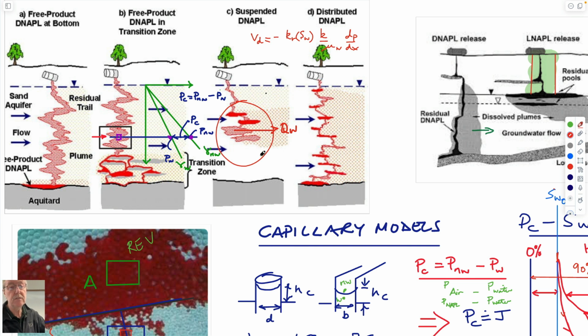And so the question you could ask yourself is, what is the rate of flow that you'd get across this chimney? Because the rate of flow that you get, I suppose, would be the volumetric flow rate, as we'll talk today, is going to be a cross-sectional area of flow times a hydraulic conductivity times a gradient of head.